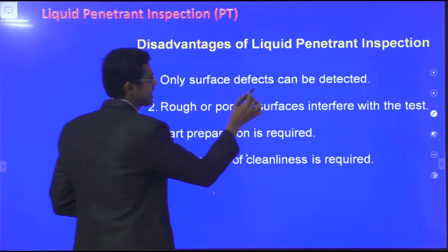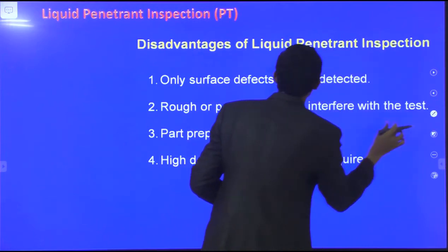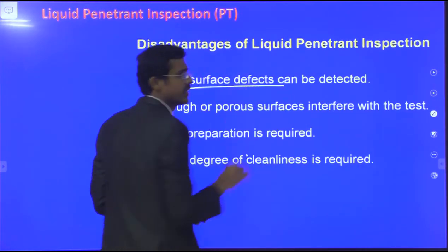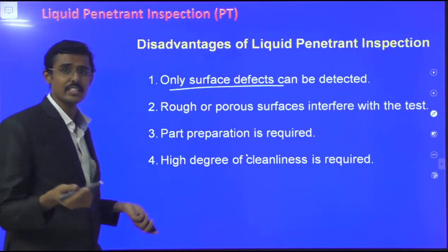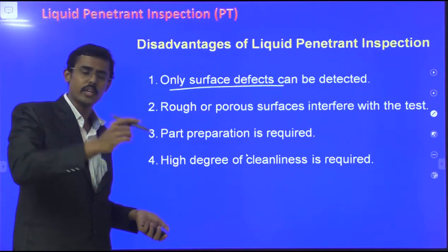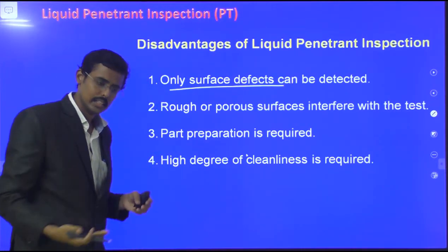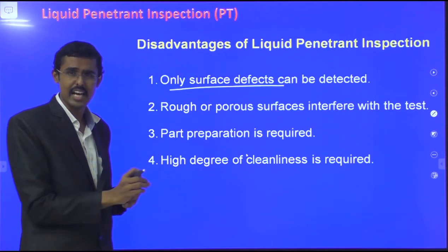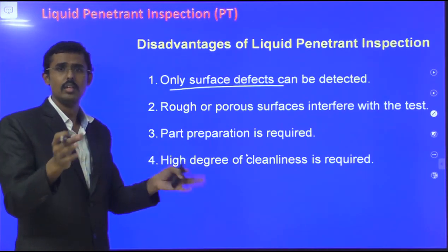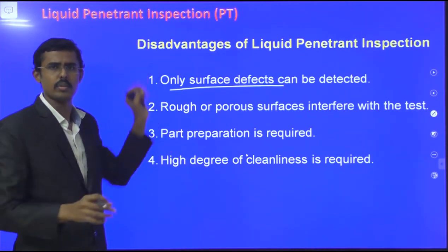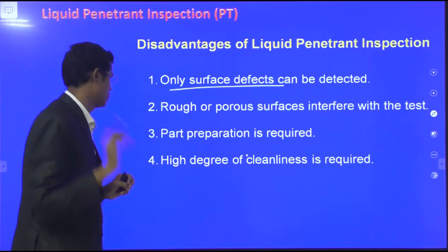Only surface defects can be detected. Subsurface defects are not possible, because the liquid penetrant flows over the surface only. Subsurface defects such as slag intrusion cannot be found by the liquid penetrant test. Radiography or ultrasonic testing can be used instead.